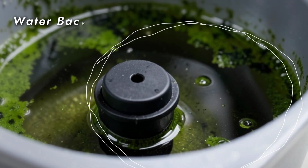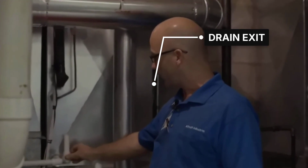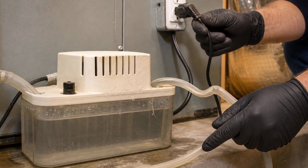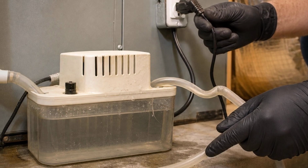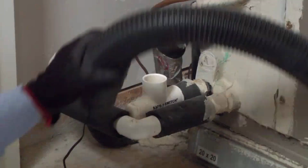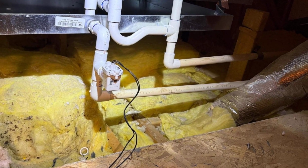A raised float indicates that water has already backed up. Investigate why it could not leave before considering any preventive treatment. The float can lower after the pan empties, and that creates a second question about why the water collected there. Treat the float switch position and visible water as diagnostic information. Check the backed up drain before accepting a major equipment diagnosis, and restore drainage before returning the system to normal operation. The switch does not clear the pipe or identify the obstruction.